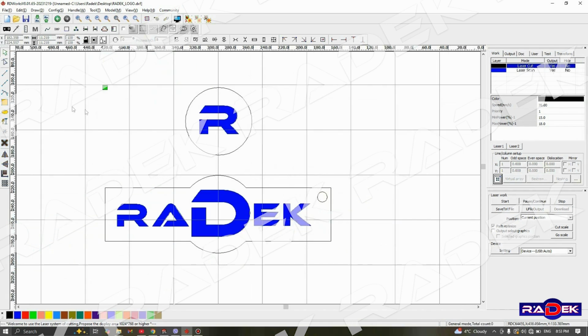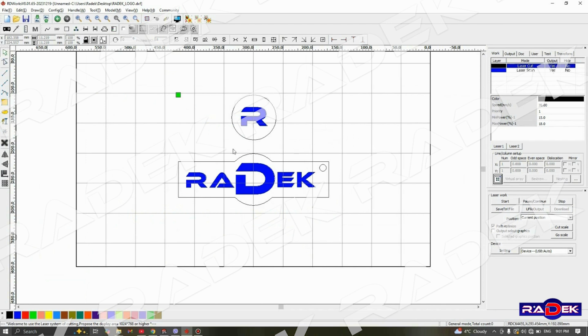Next thing that I'm going to do is change the dimensions of my design so that it has the adequate proportions. On average, every keychain has length of 70 to 80 millimeters, so I'll need to change that. I select my design and I'll need to locate the size bar where I can change its proportions. This bar can be found in the section for vector transformations located in the upper left quadrant of the software's interface.